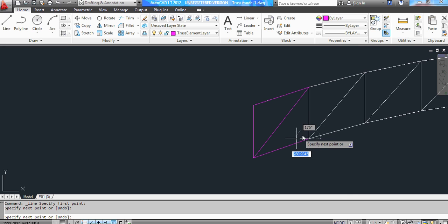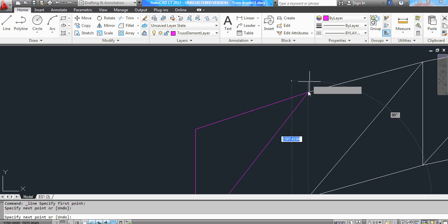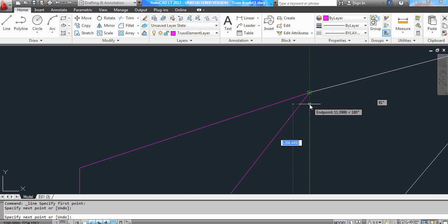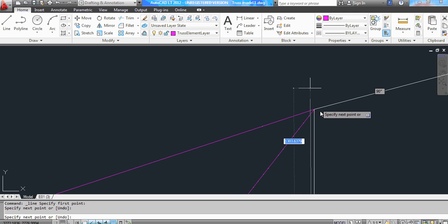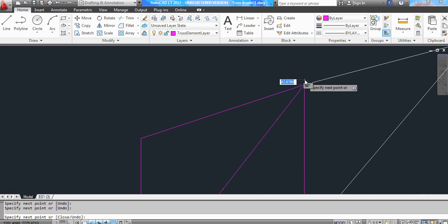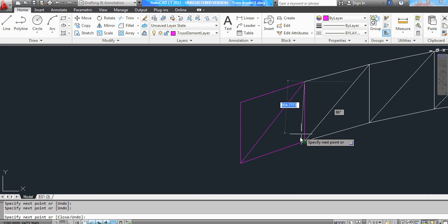Because if, for instance, you are working off a truss that somebody else has done, you cannot really be sure if the lines are connecting. Number one, you cannot be sure if they are double lines, because in AutoCAD I can draw another line this way and they will appear like one line, but when the software is reading it off, it's going to read it as two lines, and then the truss is likely to have trouble also.